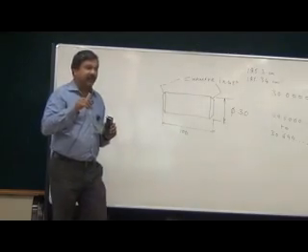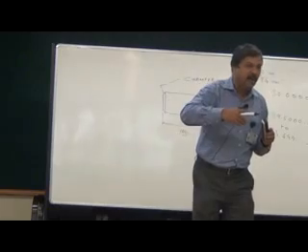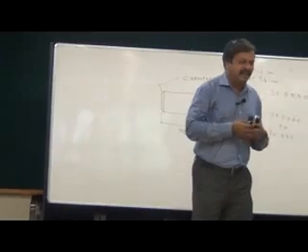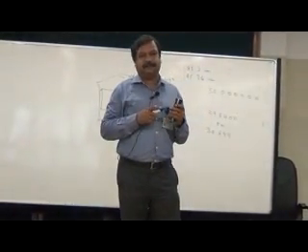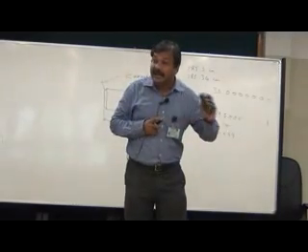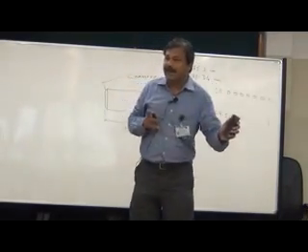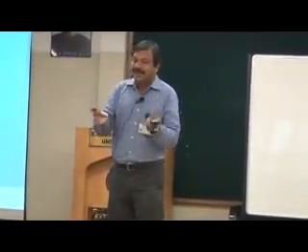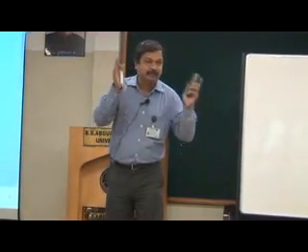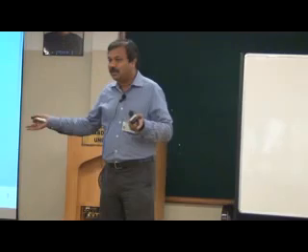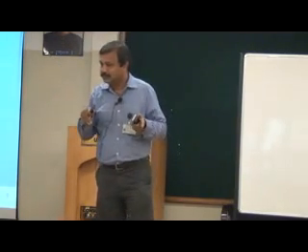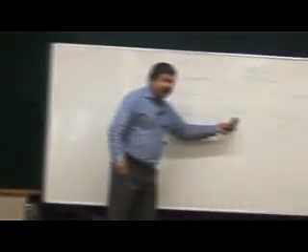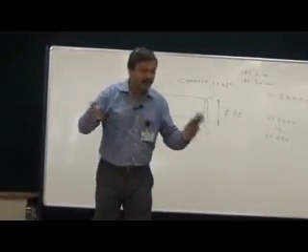Now the second thing is, whenever you ask a person to manufacture something, he cannot manufacture anything to exactly 30 mm diameter. No one can manufacture. Any accurate machine cannot manufacture a product which measures exactly 30 mm. Exact 30 mm doesn't exist in reality. Then where is the question of manufacturing? You understand? So, making something also requires a tolerance band.